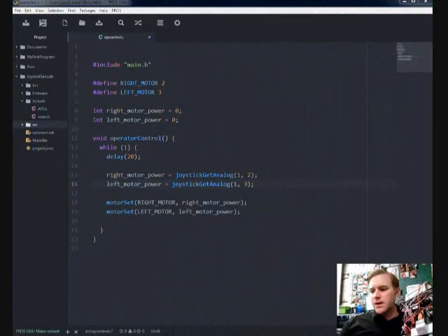Okay, so I'm back. I had a little issue with that. My advice in order to fix the issue that I was having, it wasn't connecting for some odd reason. So I just left my Cortex off and then unplugged it and plugged it back in. I'm going to leave my Cortex off when I compile and download to the robot, or build. I gotta get used to saying build too. Build and then upload it to my robot.